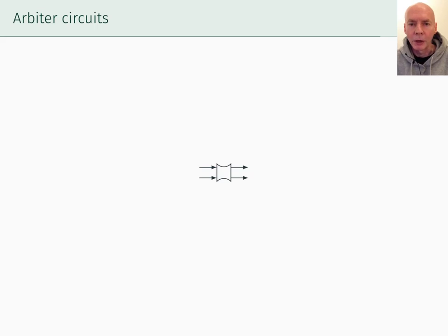Some people find that hard to believe because we're taught in school that all digital circuits can be made from logic gates. Smart people who understand things about transistors can design an arbiter circuit, but then a critic might say, that arbiter circuit of yours is prone to a permanent state of indecision, also known as metastability, if it happens to receive two input requests at the same time. And someone else will say that argument depends on Newtonian physics, which is wrong.